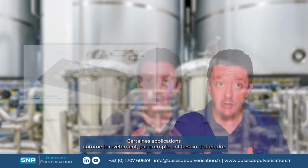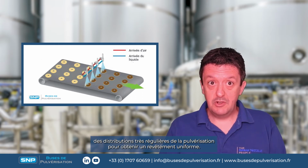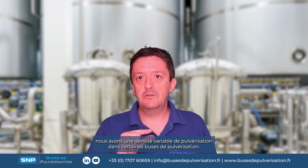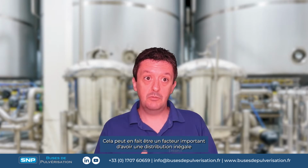So why is this important? Some applications like coating, for example, need to achieve very even distributions of spray to achieve an even and consistent coating. For some applications, an uneven distribution of spray is actually important as well. For example, in firefighting applications, we have variable density of spray within some spray nozzles. That variable density can help carry more fluid through into the fire, overcoming heat currents. So it can be an important factor there to have an uneven distribution of spray. And for other applications, it's not really that important at all.